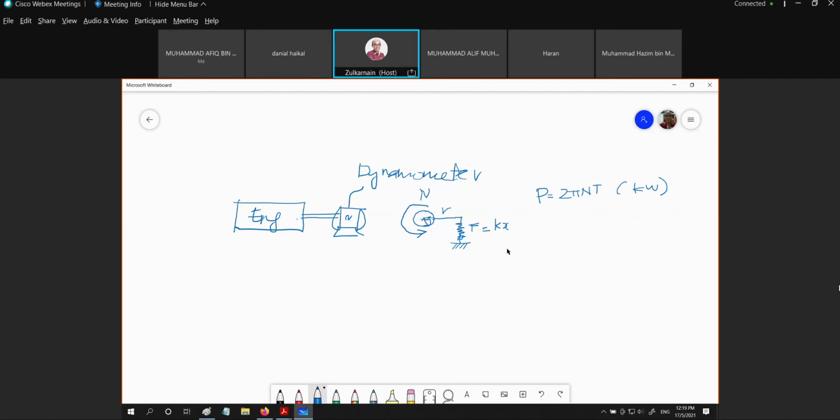Okay, what is felt by the engine because of the load from the dynamometer is as though there is a resistance to rotate. So it's harder to rotate when the load of the dynamometer is higher, right? So as though the dynamometer is braking the engine from rotation. That's why this type of power is being called the brake power.